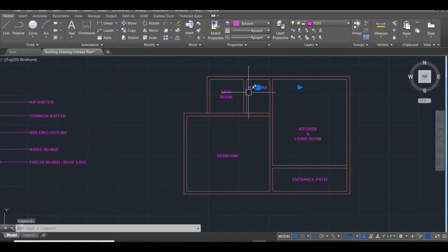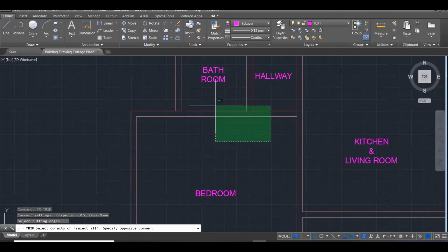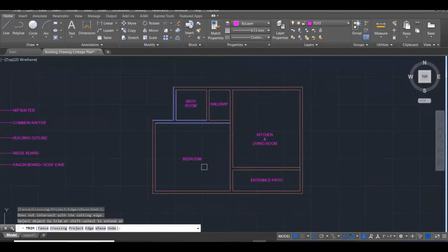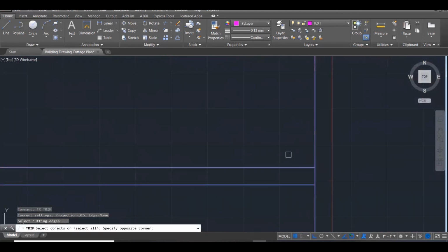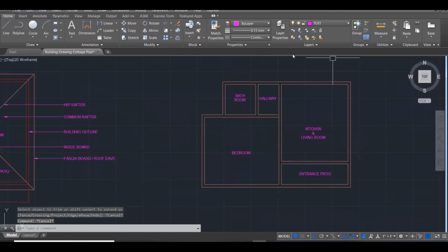Why do we connect all the walls? So that the structure is stronger when everything is connected. To make the structure strong, basically. And I'm going to clean up these points here so that when I fill, the fill will go through these openings. Sometimes when you see me cleaning up and making these channels open, that's so that when I fill once, it will go in. So imagine I'm going to be pouring my concrete in here. I need the concrete to go everywhere.